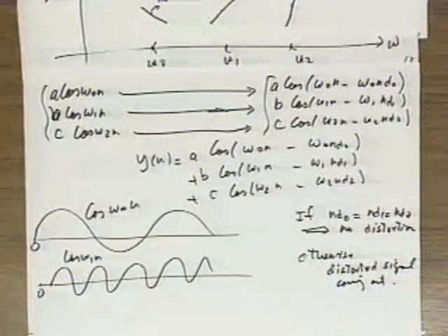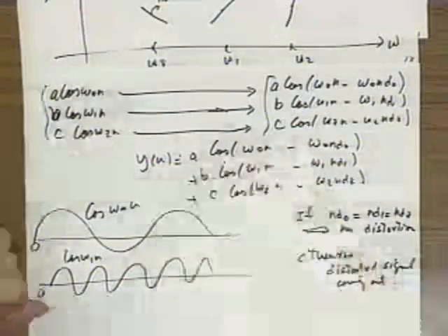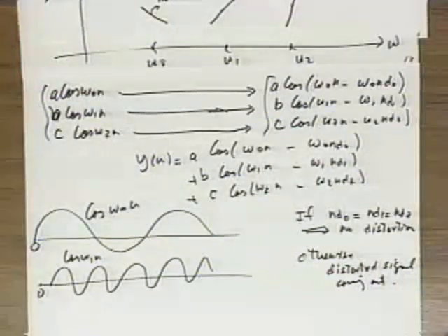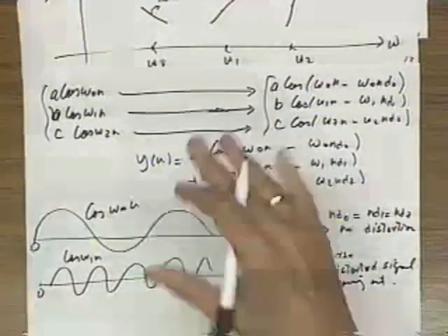Now, there was a question. I was wondering if there's a relationship between linear phase and time invariance. No. You could have time invariance and not linear phase at all. The linear phase, strictly speaking, requires time invariance: if you don't have an LTI filter, you don't have an h of n, you don't have an H of omega to talk about all of these things. So a subset of LTI systems have linear phase.